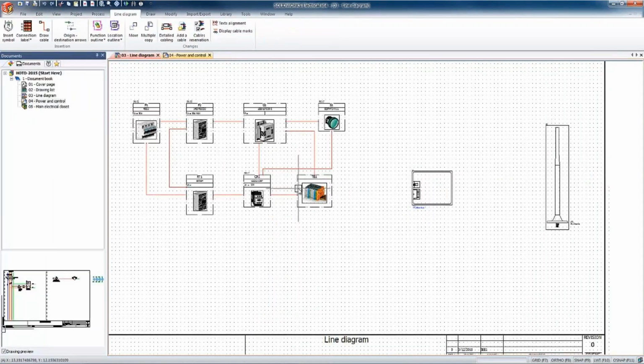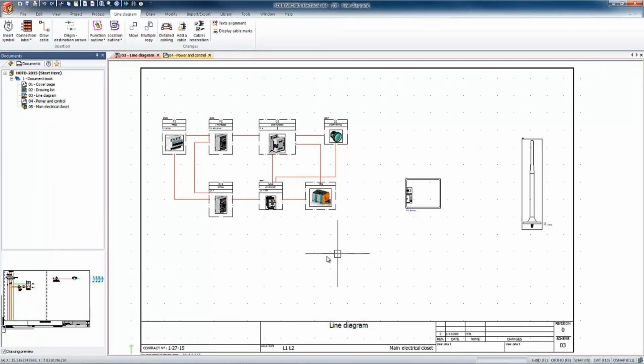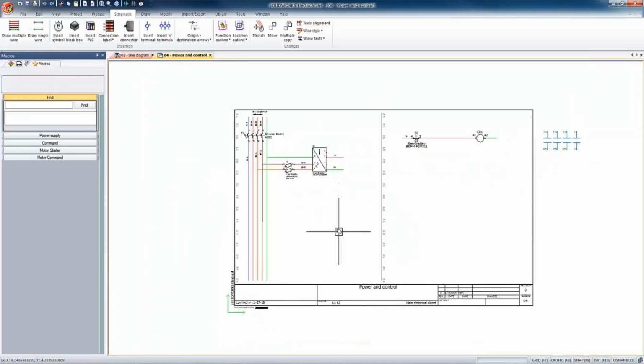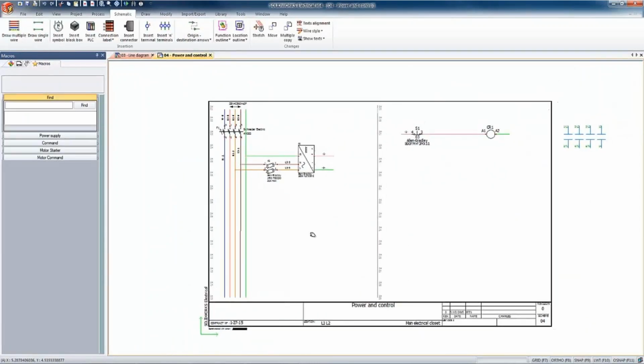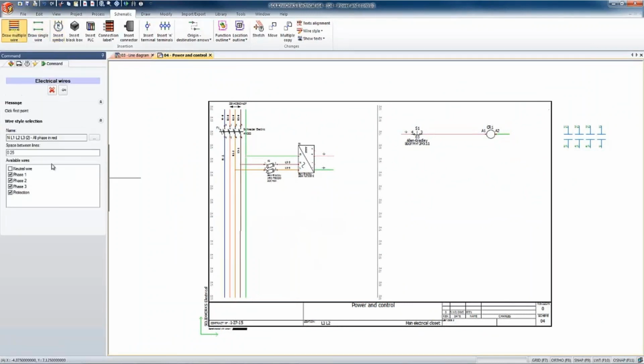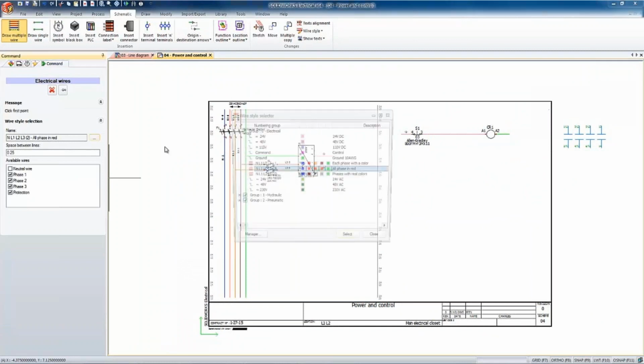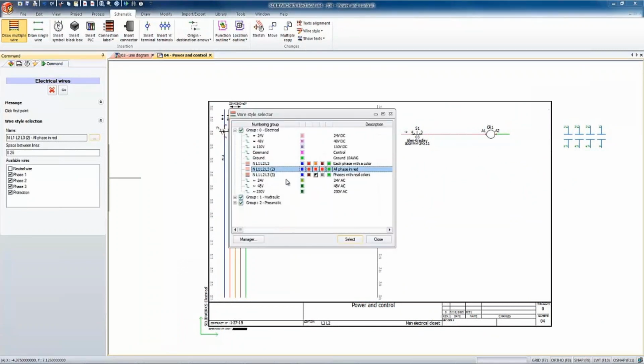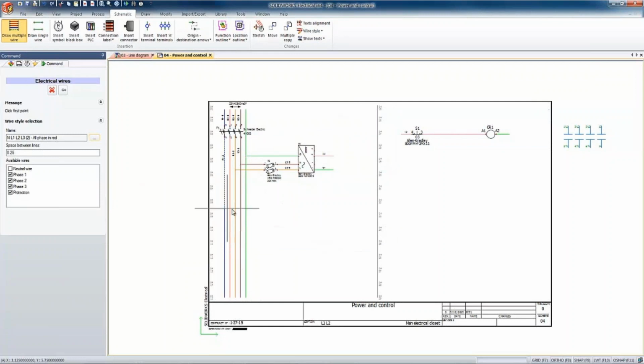So what you have in a project is just like documents. All of your documents will be in a single line diagram, multi-line diagram, and even the assembly, you can have a look at the assembly. And what we will try to do here is to connect our black box to the antenna and get a cable from the terminal to the motor. To do this, we have to complete a power circuit diagram and control circuit diagram. Starting from the wires, I will try to go through